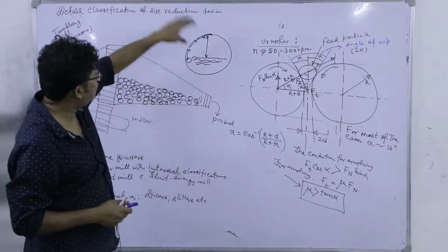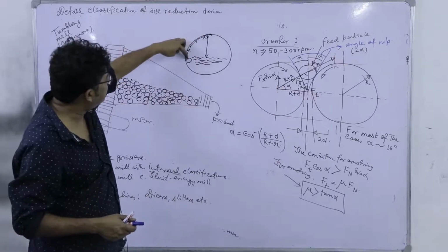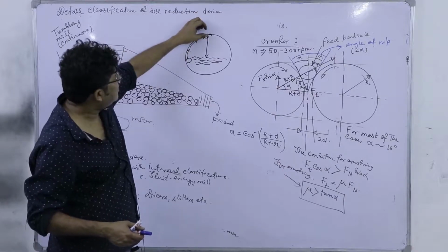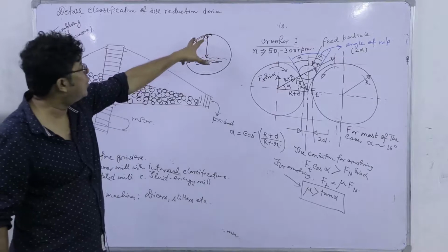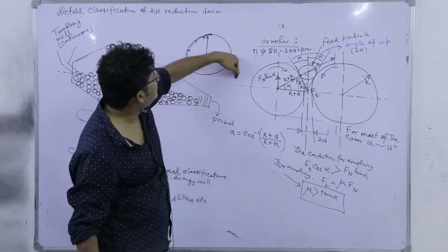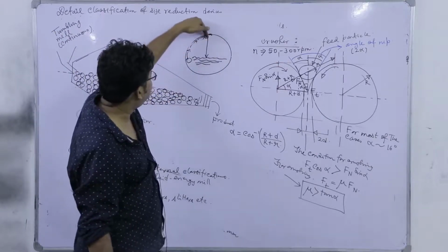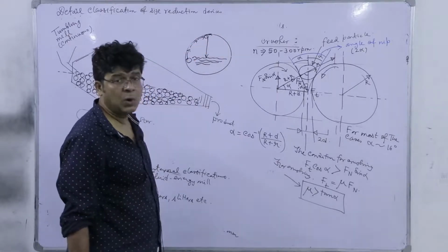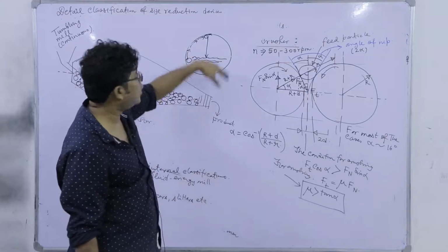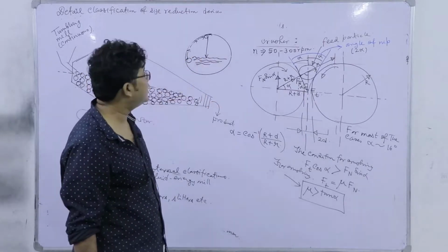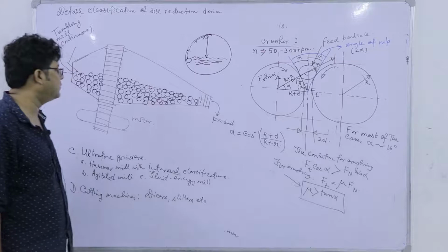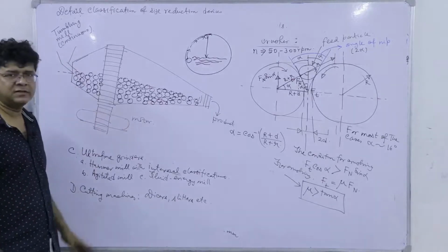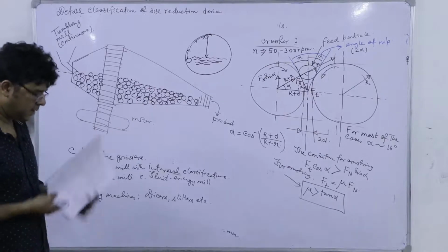As we rotate the mill at a higher speed, the balls will move to some higher height, but after some threshold of critical speed, the ball will move without detachment from the roof, going to the other side, and there will be no crushing or grinding at all, and that is to be avoided. So this is the speed limit for these ball mills. Okay? So that's why the idea of critical speed is so important.